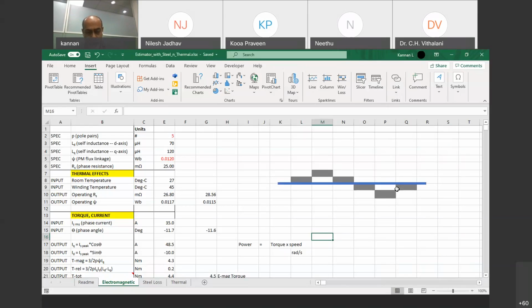And if it's a really nicely built PMSM motor, like what we build here in IIT Madras, then you will find that the back EMF is almost perfectly sinusoidal. It will be like a textbook example of a sine wave. Then it's a very good, smooth running motor.